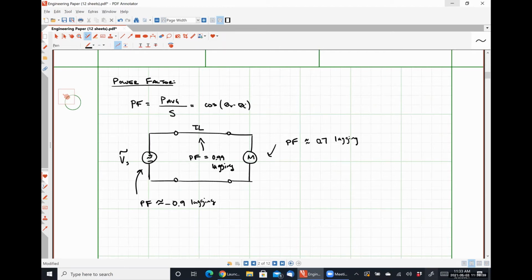But if you have that same thing and it's operating at a power factor of only 10%, then really you're going to have to design your system to be able to handle something like 40 amps of current, because that's how much inefficiency you've added into the system. Okay, so that's where apparent power and power factor come in the design process. And I'm going to give you guys a problem on your exam about that. It's very, very trivial. Don't worry about it. Okay. So you always want to make it as close to 1 as possible.